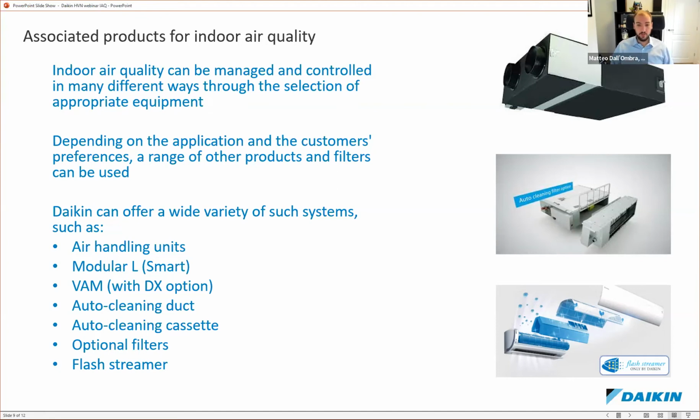So one of the first tips that we normally give is to always make sure that you run with clean filters. And of course, we know that it's not always easy or practical, because you may have many of these deployed in the field, and some might be installed in very awkward spaces, despite all the guidelines from a service point of view. That's why we have deployed this type of solution where you literally have a self-cleaning filter. A small cleaning robot periodically goes over the filter, cleans it, and collects the dust, making sure the filter is always free of buildup of particles, so it maintains its efficacy over time.